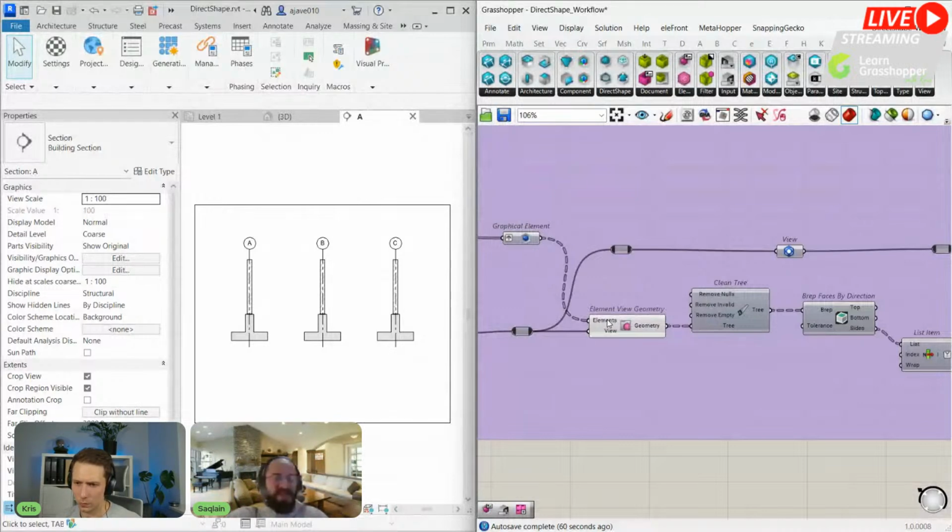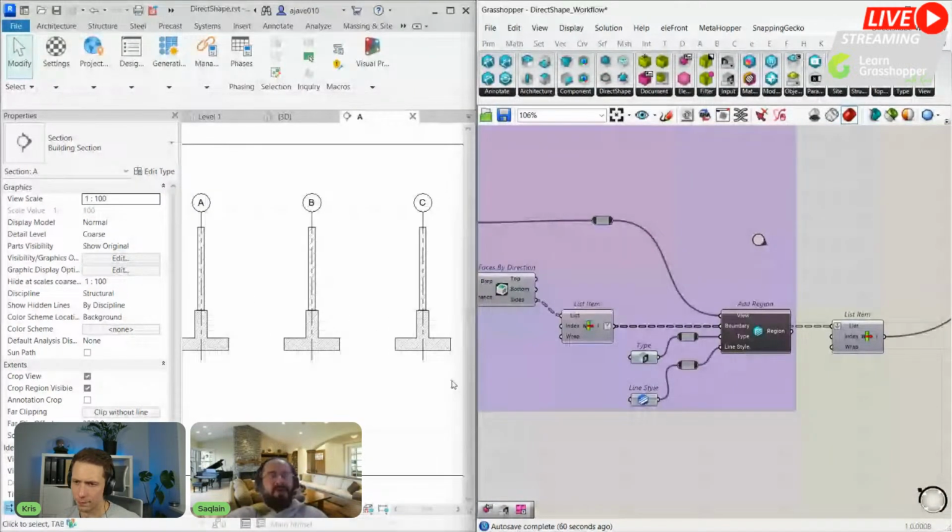and you have this region automatically there. And sometimes we had this problem of setting the region position. We had this rule that you have to show the new structure with the red lines and the existing structure with the orange line. So when you create a Revit object, the hatch from the Revit object, you don't have the option to move these hatch patterns. So you need to create a new region boundary for that.